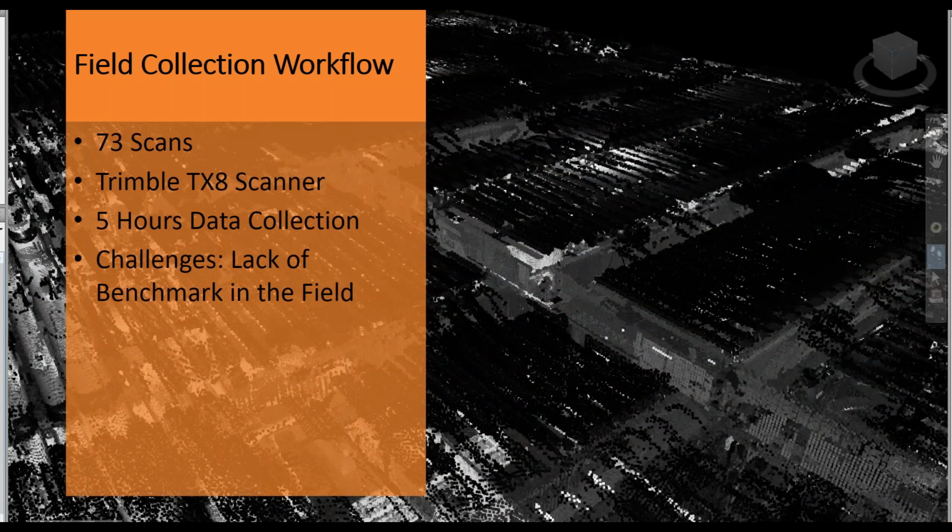Field collection workflow for this particular project, it was 3 stories. We went around the outside of the building and then proceeded to scan the interior, about 15 to 18 scans each floor, and then exterior. So it was a total of 73 scans.